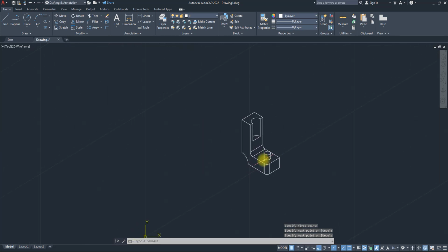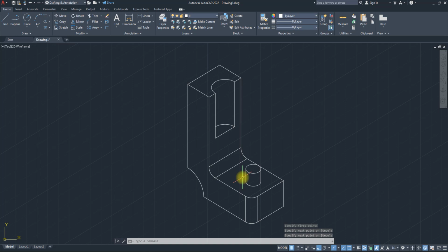So this is the line. Okay. So let's assume this is our drawing. I'm going to add dimension to it. So you know that what we normally use is we cannot use linear dimension for this guy because they are not straight. So what we use is align dimension. So DIMAL for align is the shortcut. So I will select to pick object, click on this line, draw it out. Okay, that's fine. So you can see what we're having.